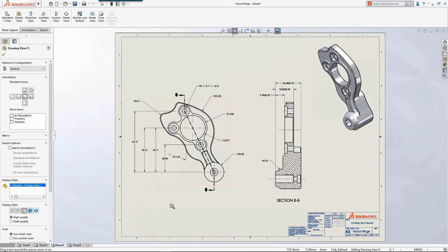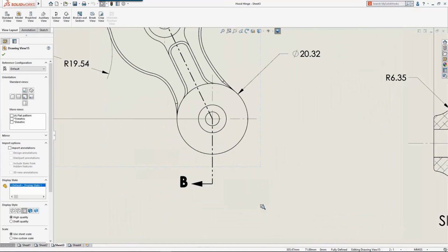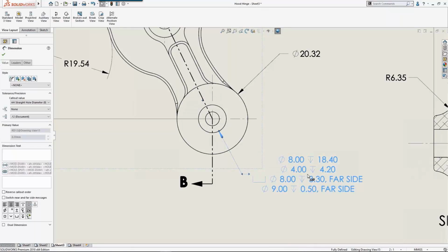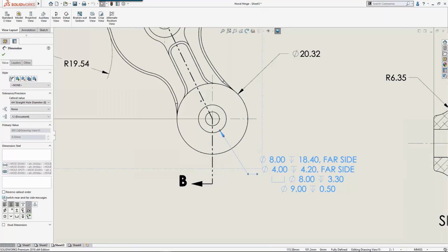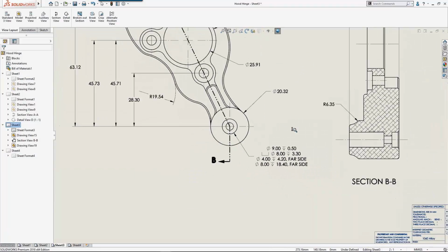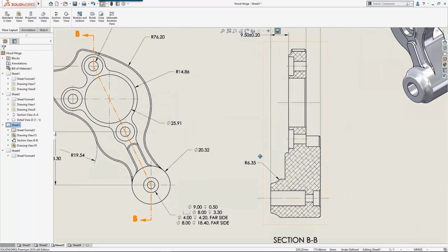The Advanced Hole feature is a powerful tool for creating complex multi-stepped holes. In SOLIDWORKS 2018, you can now quickly add easily detailed advanced holes using the Hole Callout feature. As you place the callout, new options give you control over how the information is displayed. So now you can apply all the information necessary to document multi-stepped holes in an instant.